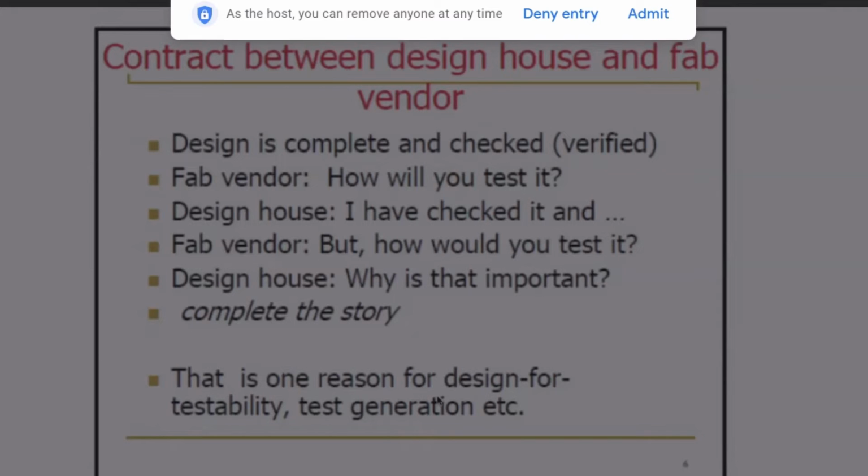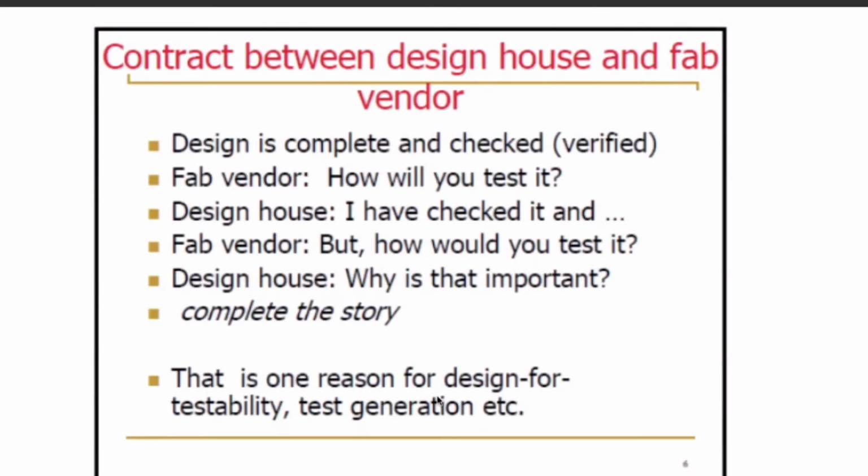But if you want to test a sequential circuit or real-time hardware that has memory elements, like flip-flops, then you have to apply some strategy to initialize the memory content, the flip-flop content, so that the memory can be turned into a known state.